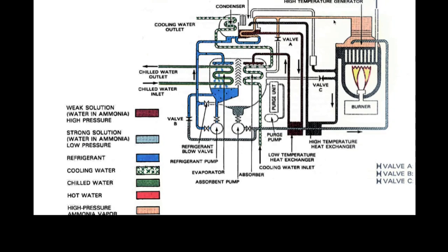Now, of course, there is also the lithium bromide system that's used in HVAC. We've been talking industrial ammonia refrigeration, but we do see things like this in HVAC, but instead of water being the absorbing medium, the absorber is full of lithium bromide solution, and water, in fact, would be the refrigerant boiling under a very deep vacuum. Hopefully you had an opportunity to see the lithium bromide absorption chiller in the SAIT powerhouse. It uses steam coils as a heat source, and there you go. You can research it. You can see what they actually look like.